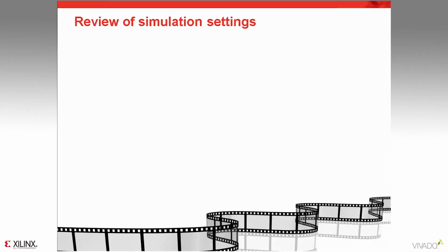Now that we have completed Xilinx HDL library compilation, the next step is to ensure that we have the correct simulation settings in place. Let's review the key simulation settings you need to be aware of before running a simulation. The simulator language option is a key simulation setting since it will alter the simulation output products for Xilinx IP. The recommended setting for optimal performance is mixed. If you want to know more about the behavior, refer to UG900 or the Logic Simulation User Guide.